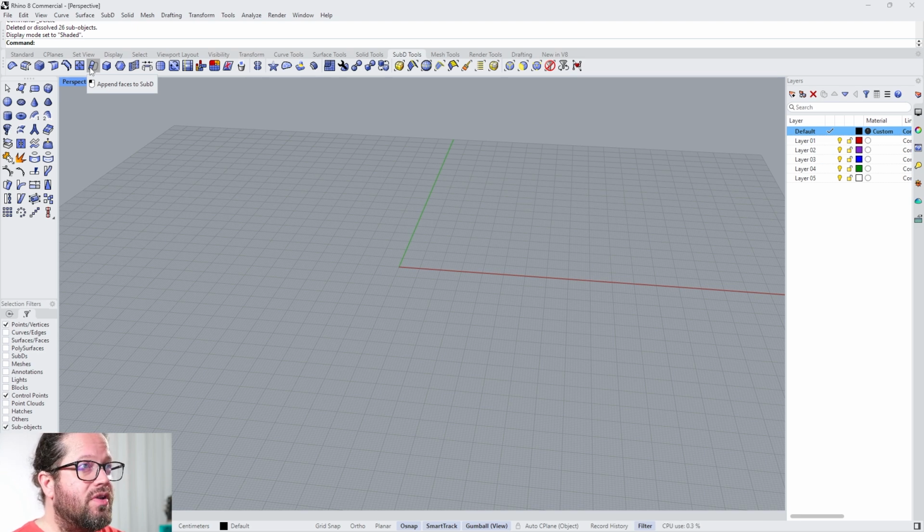A pen surface we will use a lot. We will probably use the SubD inset, SubD edges. We will use the stitch function, the mesh or SubD bridge. I will explain a bit about SubD, because what this means is subdivision. Very quickly, we can spin edges. We might use that a bit. We also will probably use the slide SubD edges, and very important, because it's a symmetric model, we will use the reflect object tool here.